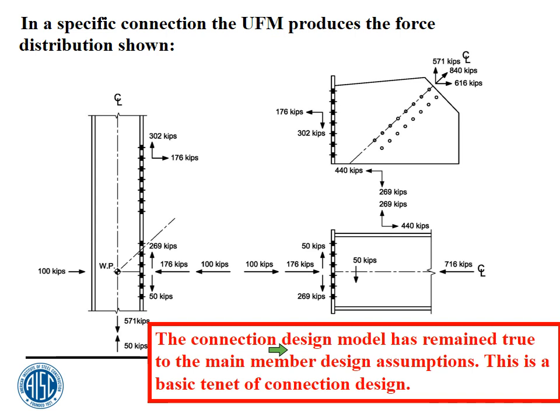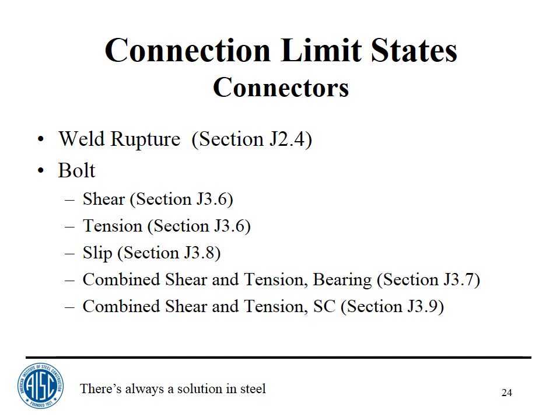I'm going to go back to slide 24. This is in regards to welding. When you were going through the different sections and where you'd find limit states, you mentioned that the check for weld yielding went away, and only rupture. Can you explain further on that? I guess the question is, can I explain further why the yield limit state on the base metal adjacent to welds has gone away?